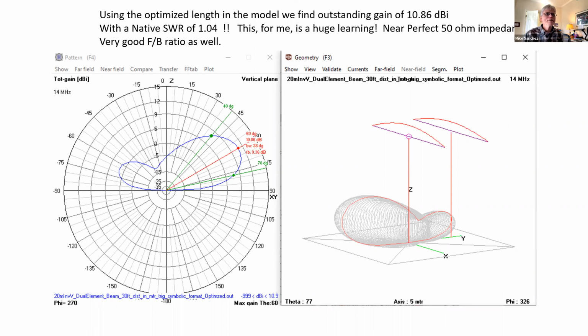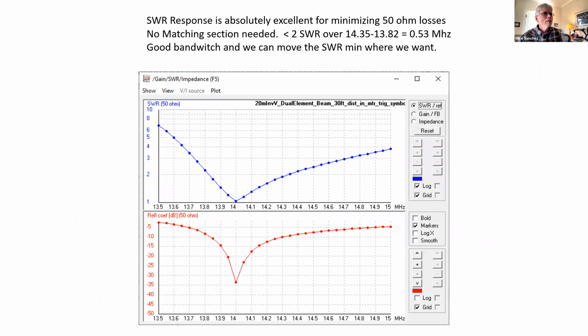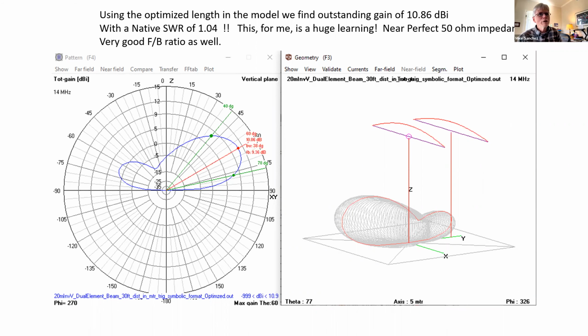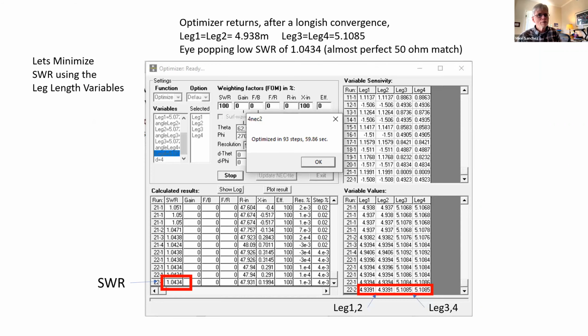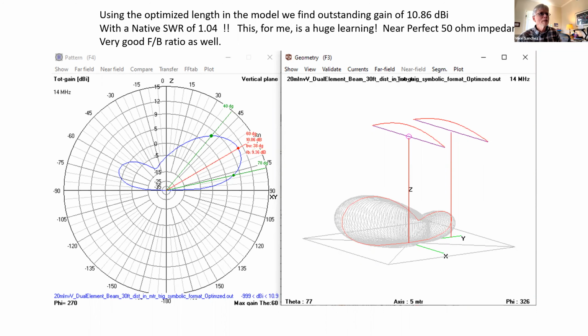So I've never done that, but the explanation that's been presented totally explains why, if your manufacturer is using dBd and they have simulated in free space, their numbers will be fantastically lower than these. But the relevant thing is the 2-element beam compared to the dipole, which we're familiar with, is roughly 4 dB improvement, which is nothing to sneeze at.